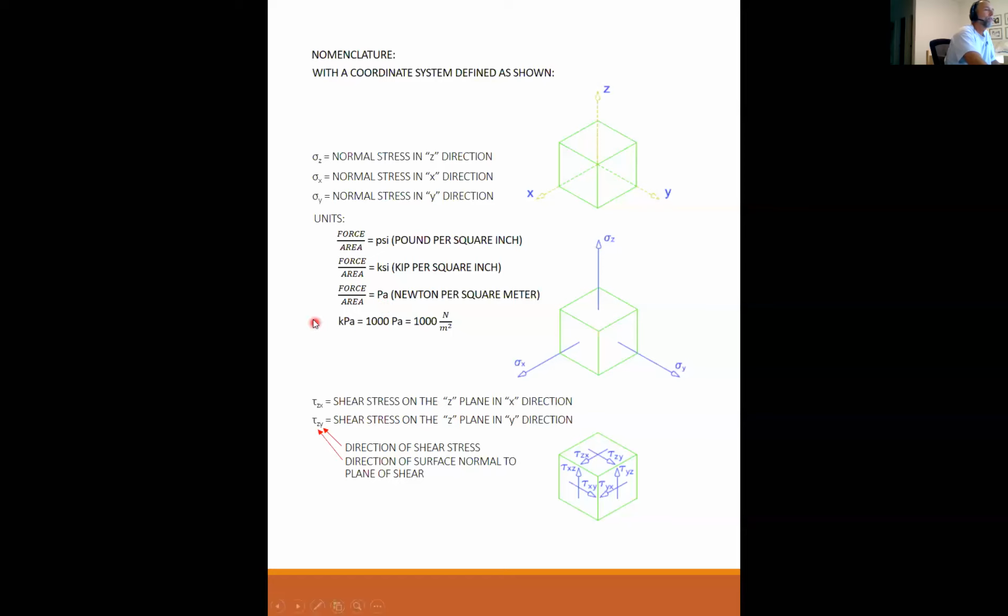So that means that 1 Pascal is not a whole lot at all. That's why we invented kilopascals, which is 1,000 pascals or 1,000 newtons per meter squared. We have megapascals. Now we're getting somewhere. A megapascal is 1,000,000 pascals or 10 to the 6 newtons per meter squared. Megapascals come into the strength of concrete.